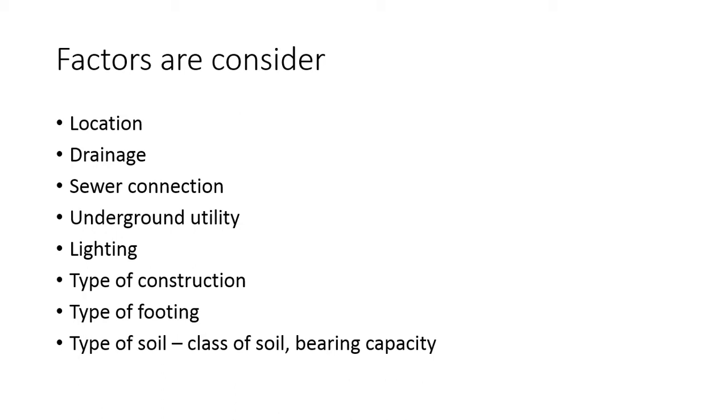Are we going to put a pit and connect the downpipe into the pit, and from that pit a PVC pipe into the kerb using a kerb inlet connector? So these are the considerations we need to give. Sewer is the main consideration. Sometimes the site is located off the road, where there isn't much sewer connection facility available. If that is the case, how are we going to get the sewer out using a detention facility, and how are we going to pump out an effluent system, and how are we going to design it?